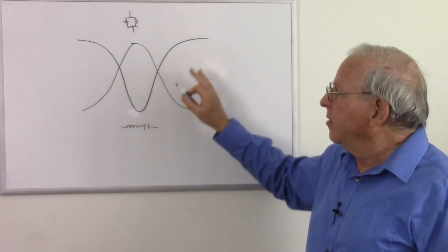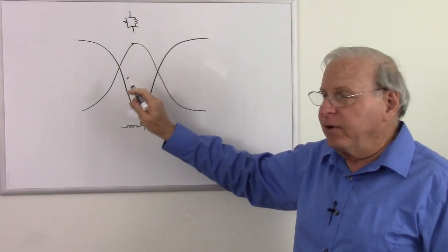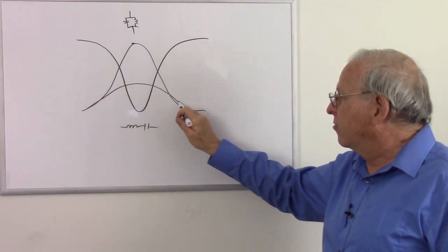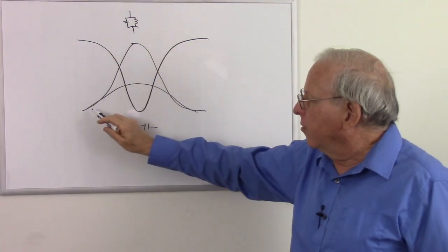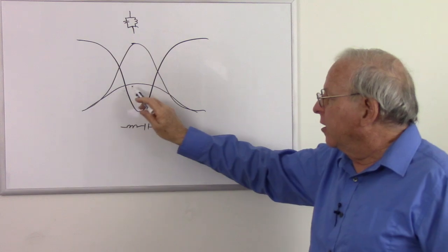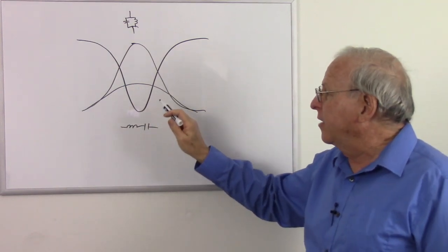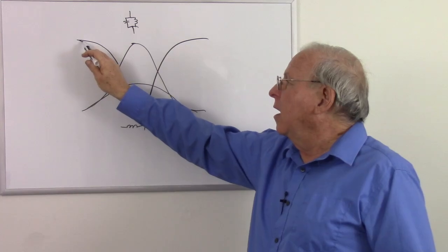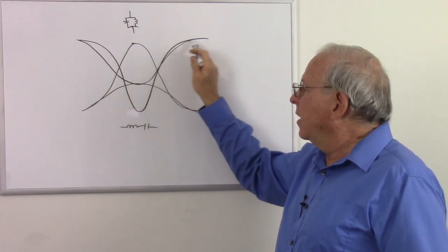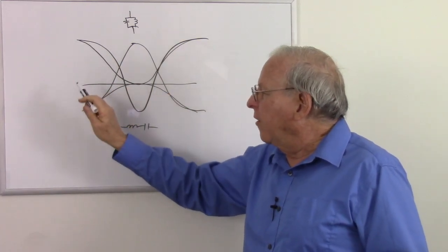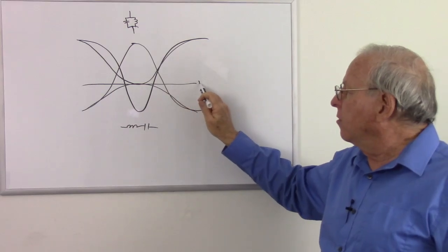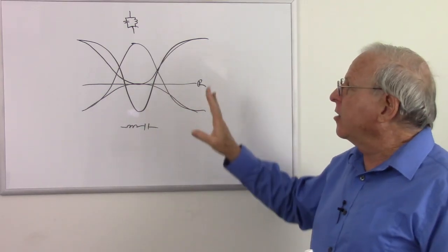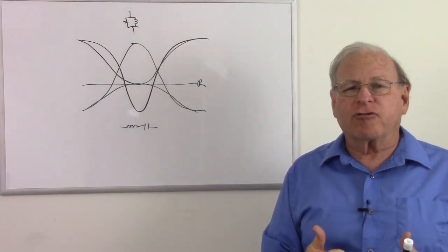And we talked about some of the other characteristics, like if we add resistance, it's going to change the response of that. So in the parallel circuit, it'll lower that peak and broaden the range of frequencies that tend to pass, and the series circuit will tend to do the opposite. And we remember that our actual impedance will be equal to our resistor if we have resistance in there. But what we're going to look at today is how we can manipulate this to create electronic filters.